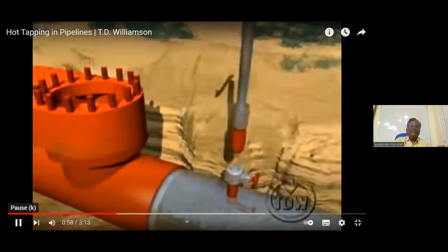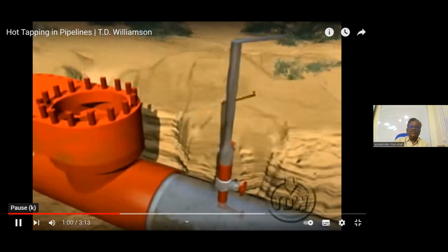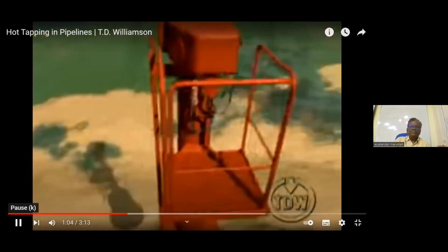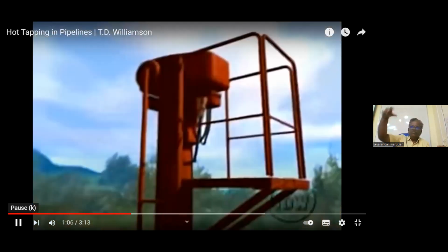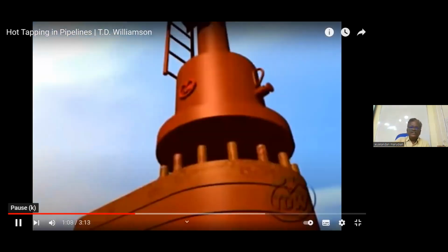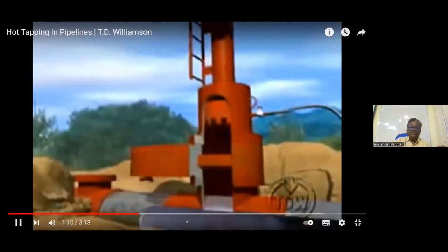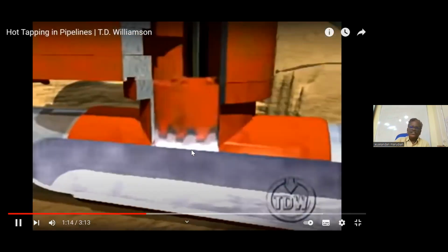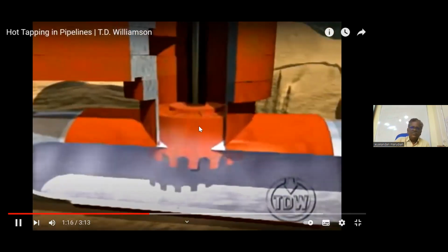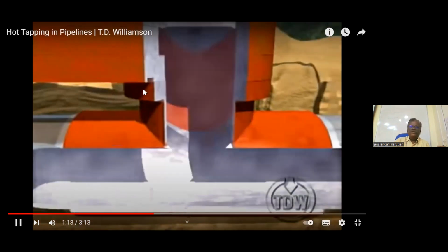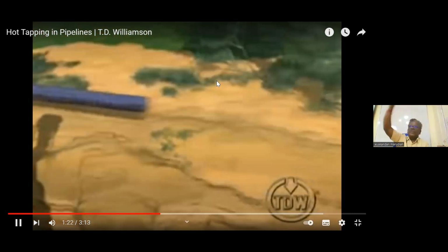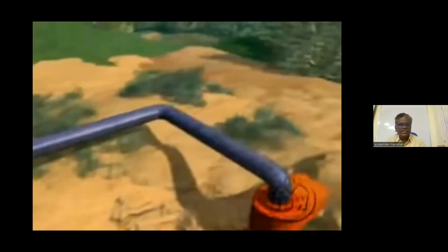this is called the hot tap machine. This is a hot tap machine, which is going to make a hole on the plate. It will be installed above the valve, and there is a liquid flowing here. It will cut using a cutting tool. Once it cuts, the liquid will come, we will close the valve. That's all. We will close the valve and remove the machine. After that, from the valve, we can take a nozzle connection. That is called hot tap.